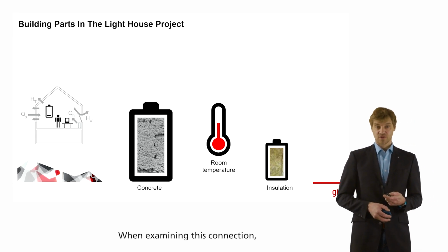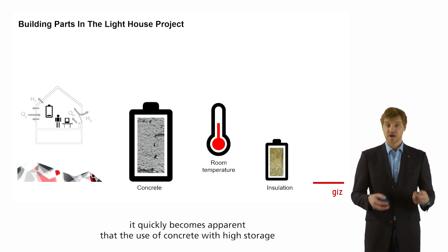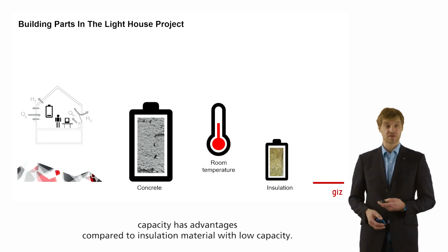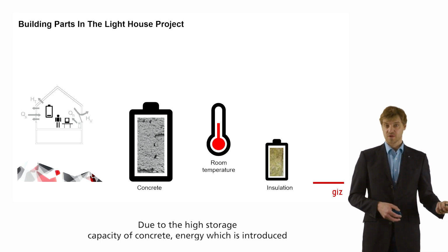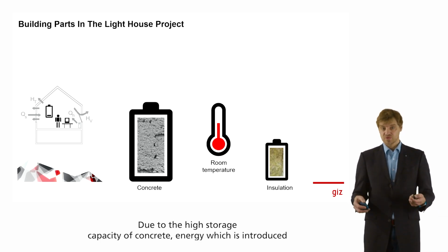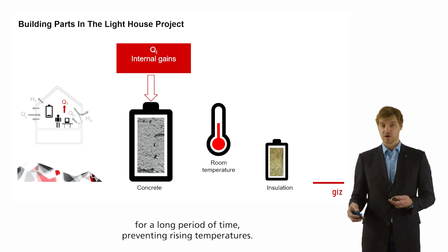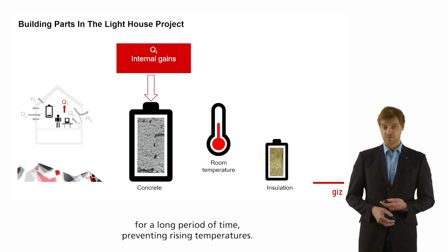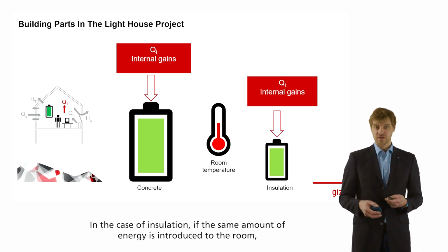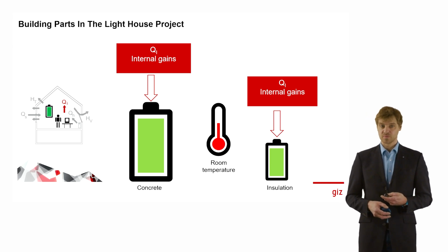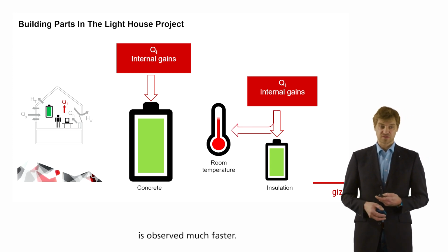When examining this connection, it quickly becomes apparent that the use of concrete with high storage capacity has advantages compared to insulation material with low capacities. Due to the high storage capacity of concrete, energy which is introduced by internal or solar loads can be buffered for a long period of time, preventing rising temperatures. In the case of insulation, if the same amount of energy is introduced into the room, an increase of the room temperature is observed much faster.